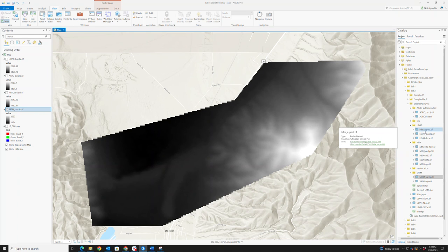But in the lab, I also ask you to make hillshades, and you might even consider making a curvature map. Although it's not required for this lab. Let me show you a few examples of these, and then you can make your own for the ones where they're not existing. So for the NED, we can see that there's hillshade, NED HS, hillshade 180 and 315. These are different sun angles. Let me add one to show you.